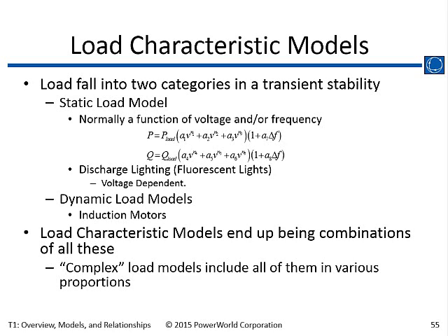Governor power flow and AGC reactions. How do you model AGC reactions? Do you care at all, or would just the governor response be good enough in a transient study? Do you care about AGC movement? The question was on the governor response in transient stability, and then later on the AGC control. Right, the AGC can also play a role in there a little bit later.